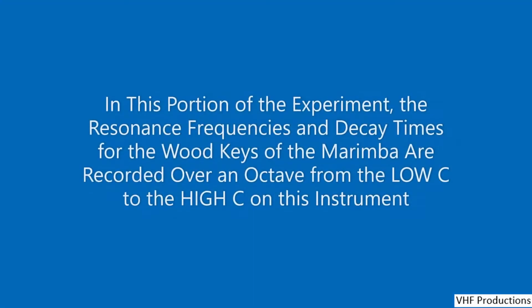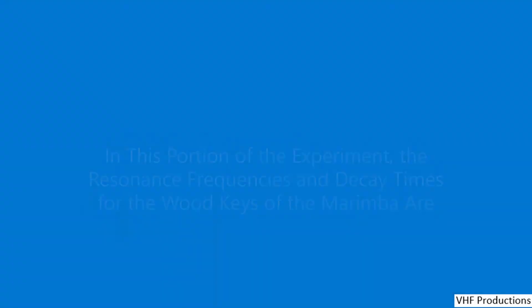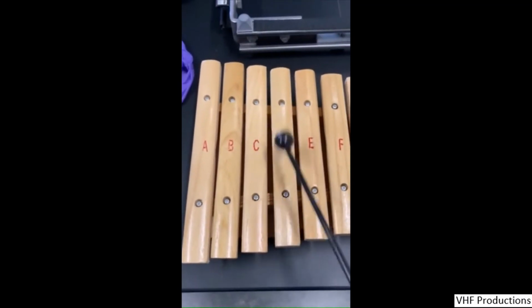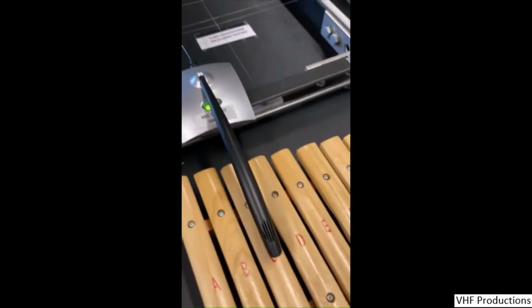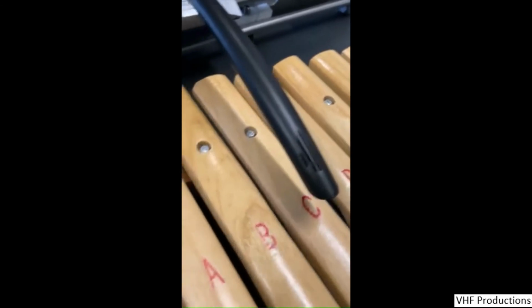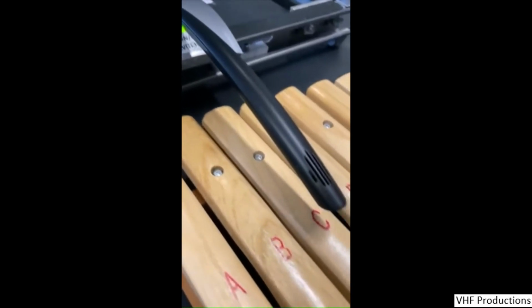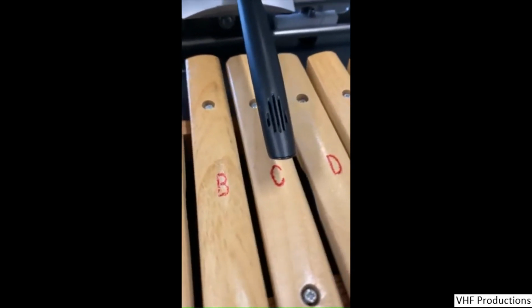In this portion of the experiment using the marimba, the resonant frequency and decay half-times of the wood keys of the marimba are going to be recorded over an octave from low C to high C. We will begin by measuring the resonant frequency of the low C key. This is the lower frequency of the two C keys on the marimba. So this one is where the span length is the largest, which leads to the more compliant distance in this octave and results in the lower frequency.